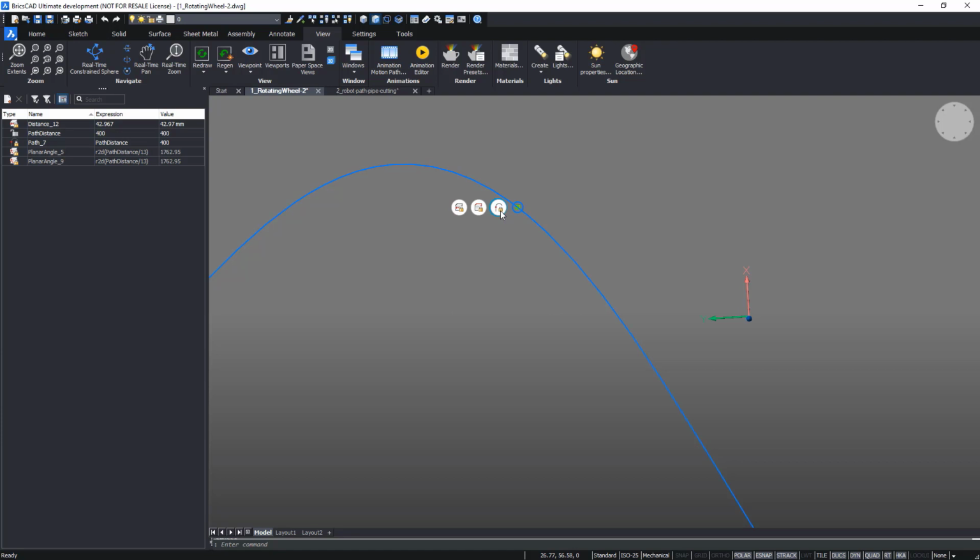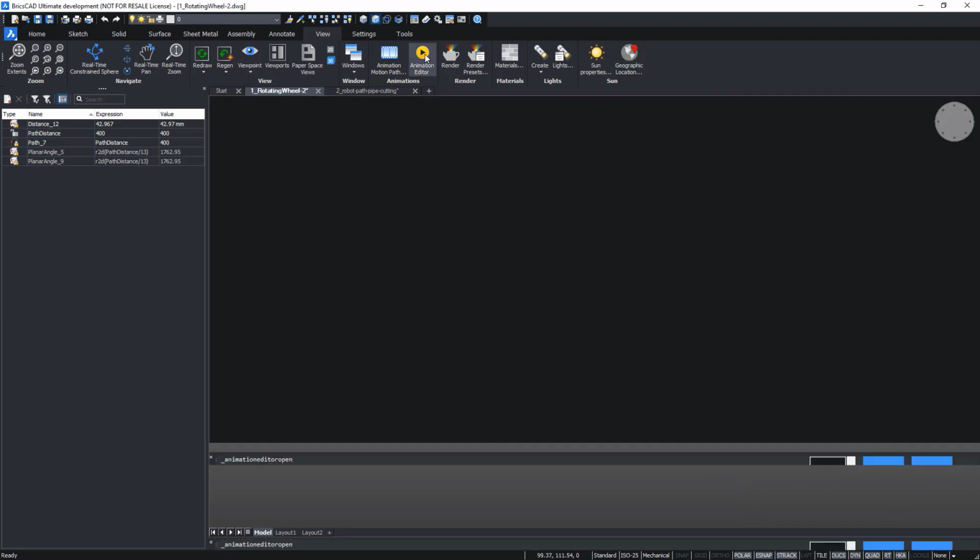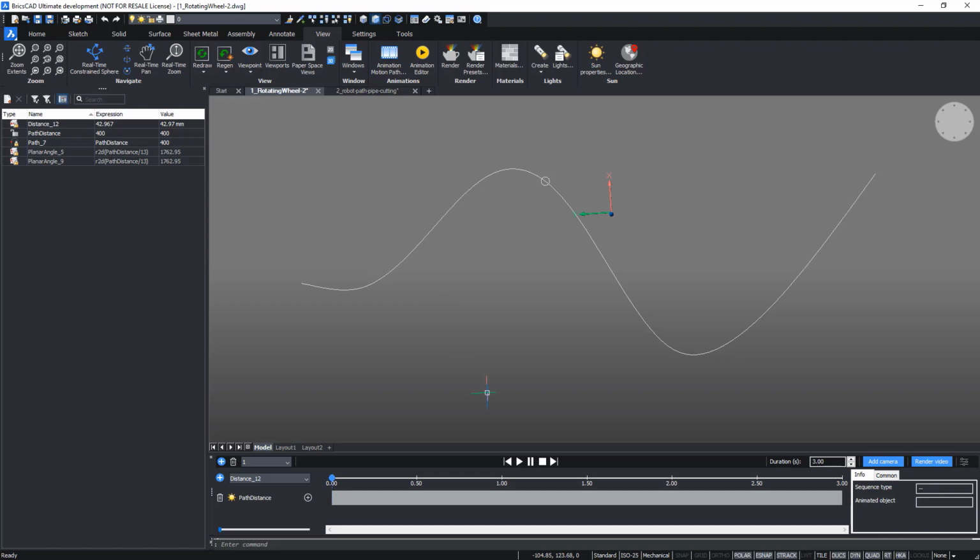This is quite a simple thing which allows you to attach a point to a curve and specify the parameter at which this point is coincident to the curve, and not only specify this parameter, but also change it and see how, for example in this case, the point can be moved along the curve. To create this constraint it's quite easy. You select the point, select the curve, and press the new button, create path constraint.